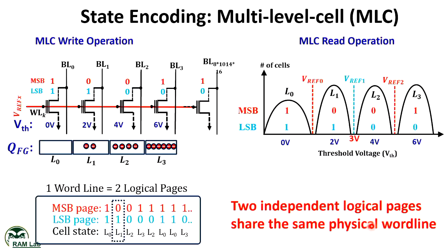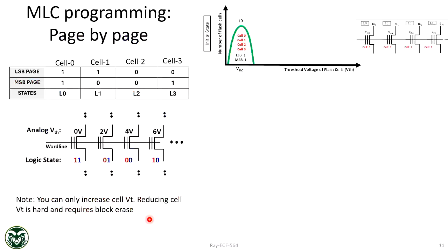Okay. Now look at how exactly we program. For example, can I program one page at a time, or do I need to program both of them together in this structure? Suppose the user stops after giving LSB data. Do you think NAND will not program that? So we said that we need 2 pages of data: LSB page 16 kilobyte, MSB page 16 kilobyte. But suppose the user just gives 16 kilobyte. So what will happen? You do programming step by step.